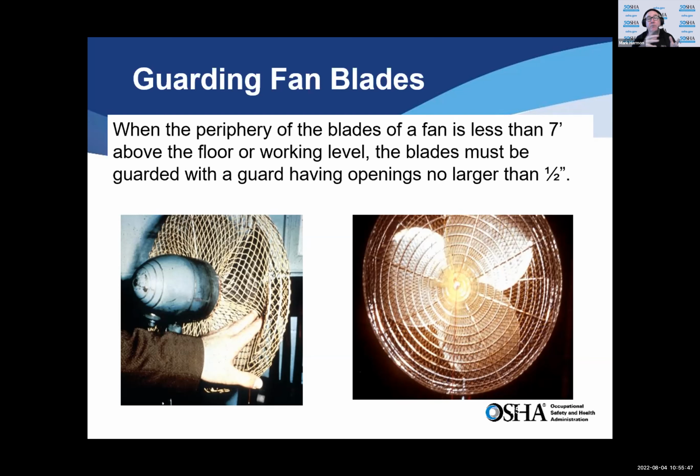Okay, again, with what we've already learned and discussed, why is it a half inch? Well, you don't want your finger to be able to touch the rotating blade. So that's why these guard openings are of such size. If you have a larger opening, then the guard needs to be farther away, so that you're not able to reach it.